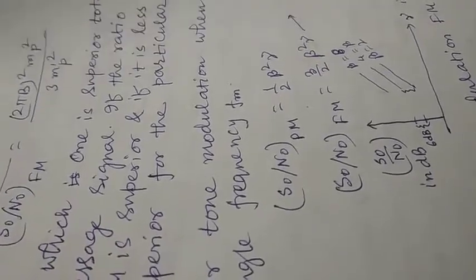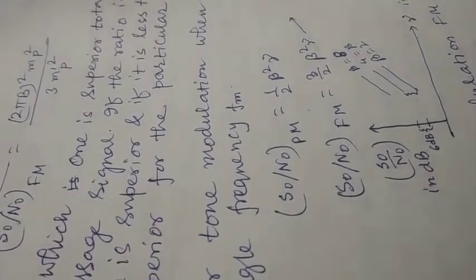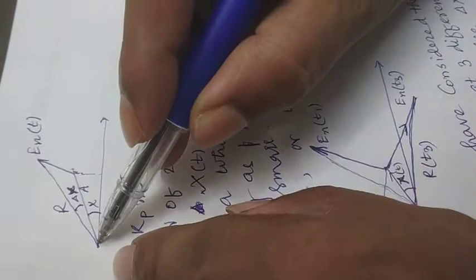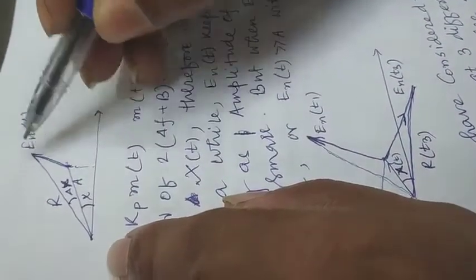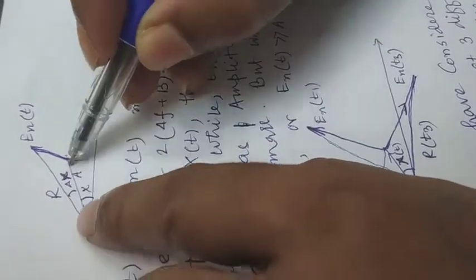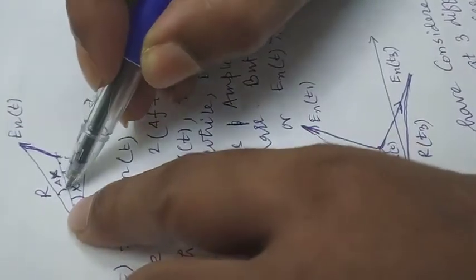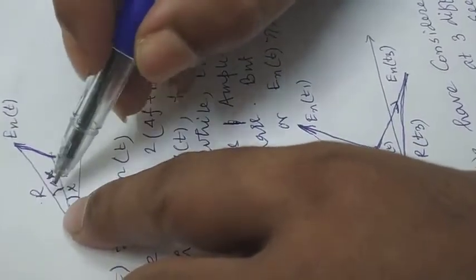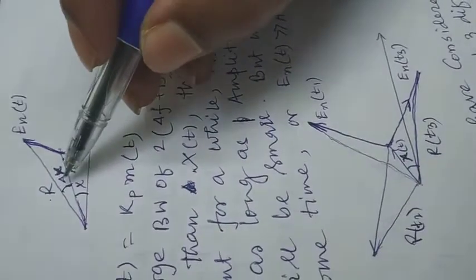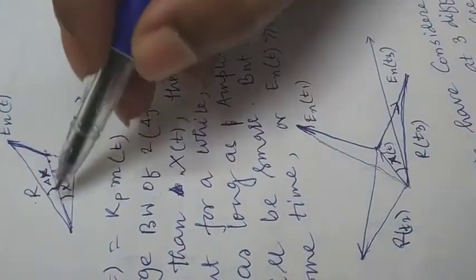And overall, there is a problem here also, that is the threshold effect, which we are going to discuss for large noise cases. See what happens here. In the case where this noise is very much higher than A, then this delta psi(t) will not be approximated as constant, or will not be small.